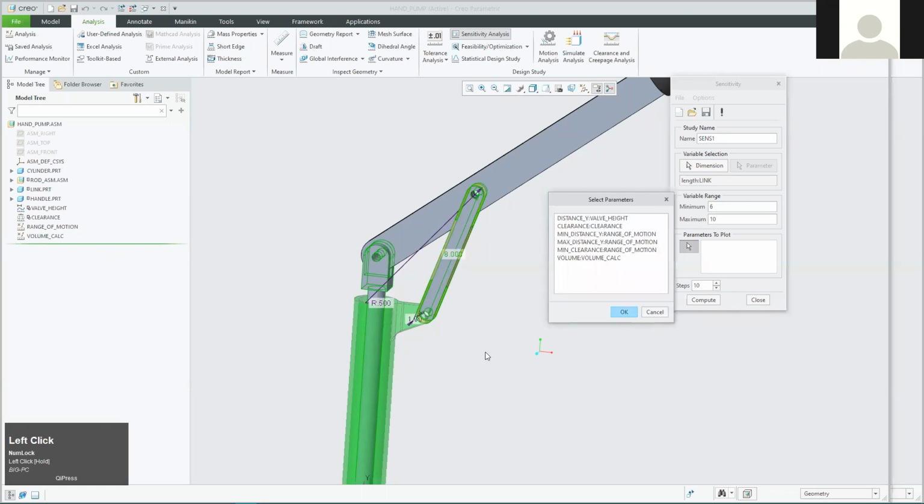So again, these are stored at the assembly level. Just like we saw that you can store parameters at the part level or at the feature level, a similar thing happens in an assembly. You can store parameters at the assembly level, which is where all these are stored, or you can store them internally within each part. And then obviously within each part, at a lower level, you have each feature within the part. So there's kind of a hierarchy going on there. The assembly sits at the top, then the parts, then the features within the parts.